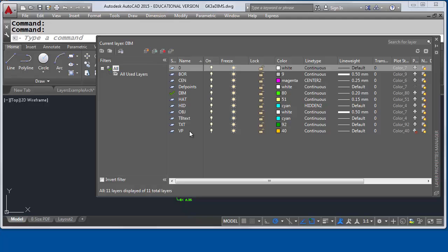are different. Layer names are specific to the industry, so if you're interested in learning more about layer naming convention, check out the information in the Graphic Standards Manual. There you'll find a really good list of different kinds of layers commonly used in mechanical and architectural drawings. You'll notice mechanical layer names typically are 3-letter abbreviations. BOR for border, CEN for center, DIM for dimension, and so on.